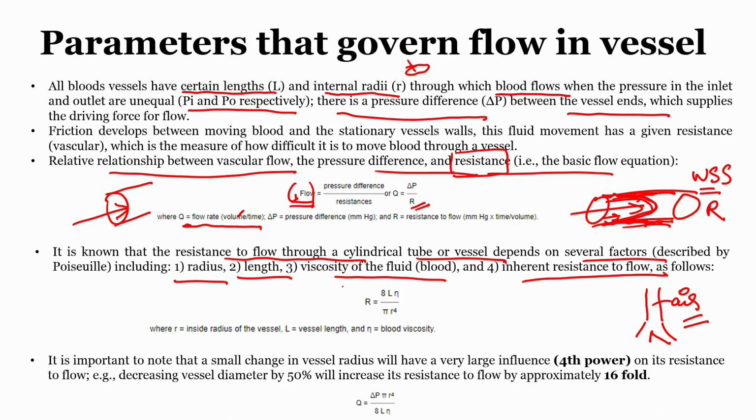Here, all the parameters put together, we have something called the resistance R. L here is the length, A is a constant which is derived when you go through the derivation, you can see how the parameter comes. This depends on the geometry of the structure, and the viscosity, here it is the blood viscosity, the vessel length and the inside radius. Now, here how is the radius dependent on the fluid flow? It is inversely proportional to R power 4.